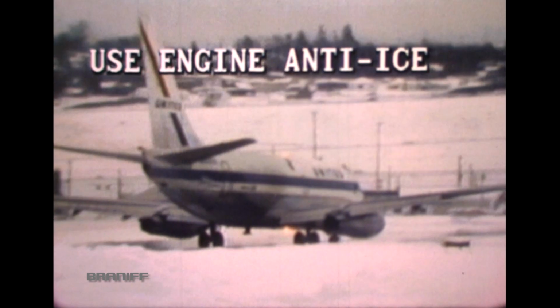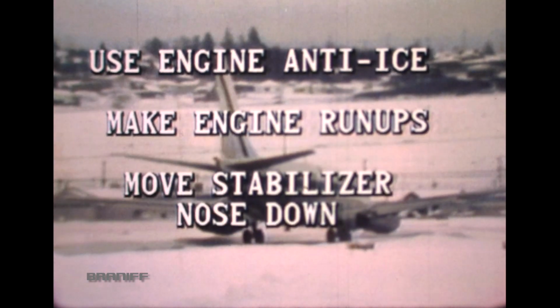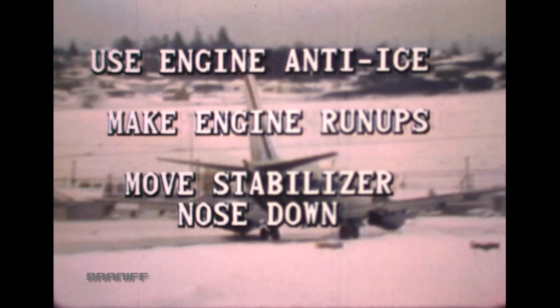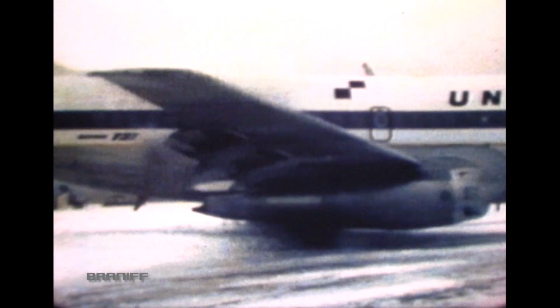Use engine anti-ice and make periodic engine run-ups. In addition, move the stabilizer trim toward the full nose-down position in accordance with the operations manual. If the landing was made on a slush-covered runway, do not retract the flaps until they have been inspected for ice accumulation. Let's now look at information sources.